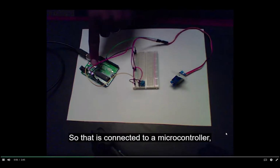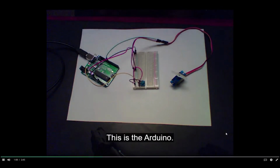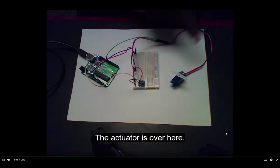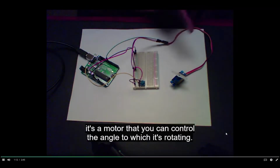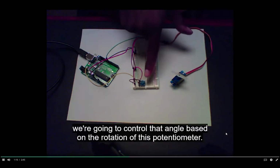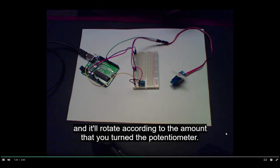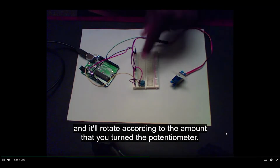So that is connected to a microcontroller. This microcontroller right here is the Arduino. The Arduino reads the information about the rotation, and based on that, it sends signals to the actuator. The actuator is over here. This actuator is a servo motor. It's a motor that you can control the angle to which it's rotated. You see it has a little arm on there, and we're going to control that angle based on the rotation of this potentiometer. So the idea is you turn the potentiometer, and the servo will rotate the amount that you turn the potentiometer.